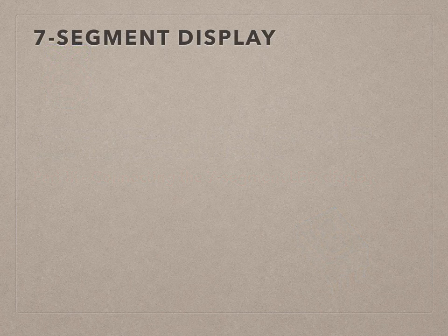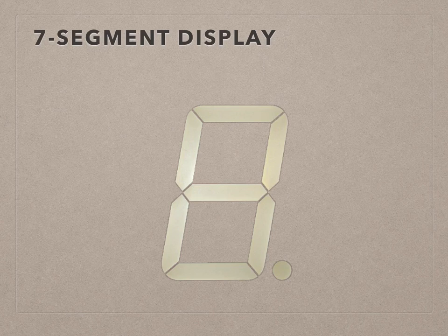Despite its name, the 7-segment display has 8 inputs, due to the 7 segments used to display the digit itself, plus one additional one for the decimal point. The segments are typically assigned a set of letters, which correspond to the pins that control the input. These start with the letter A at the top of the digit, and rotate clockwise, finishing with the central horizontal segment. To discover which segment corresponds to which control pin, we should consult the manufacturer's specifications.